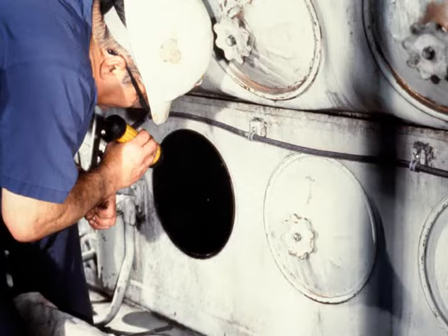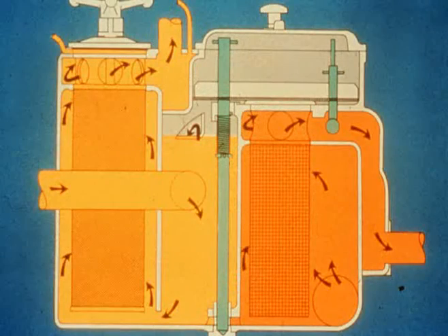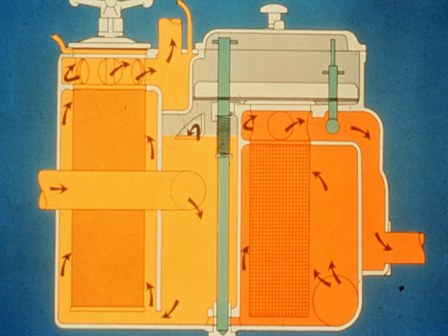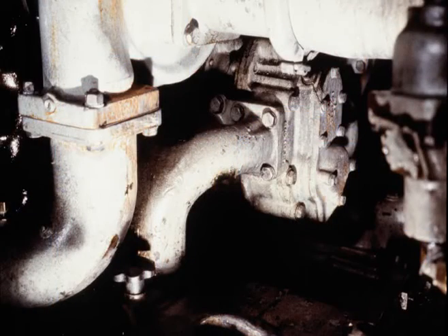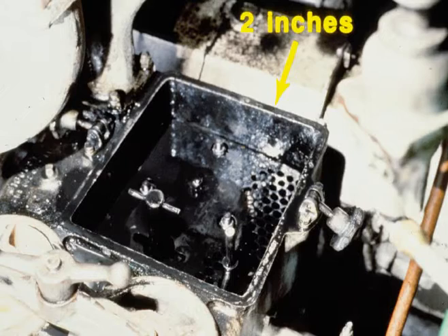To diagnose problems with the lube oil system and make any necessary repairs, you must be able to qualify the system. This qualification is made by observing the oil level in the strainer housing. If you recall from our earlier explanation of how the systems work, the scavenging pump will pump oil back into the strainer housing, and the piston cooling and main lube oil pumps will draw it out. This requires a constant oil level flowing in the housing. This level is approximately 2 inches below the screen during operation.